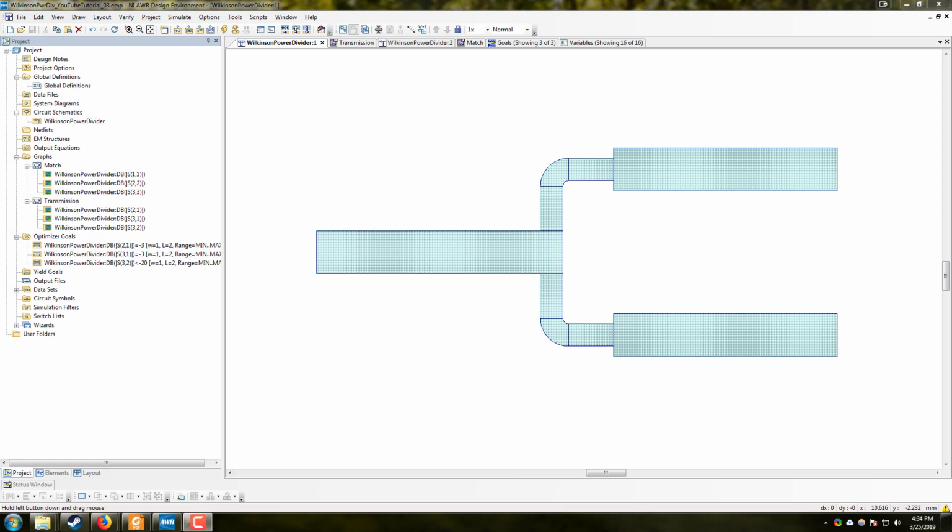When we first defined Kirchhoff's voltage law and current law as far as circuit analysis is concerned, we actually made an assumption that we didn't really do a good job of explaining early on in the coursework because it would confuse people. And this assumption is what we call the lumped element assumption, also known as the lumped element model.